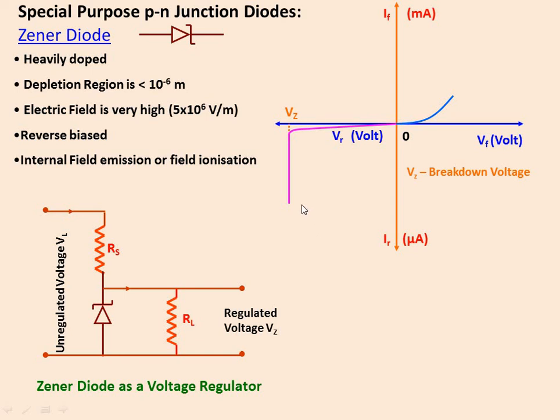But if the diode is very lightly doped, the breakdown of the junction will occur at a high voltage. Are we clear with this? So depending upon the doping we can have these particular breakdown values. Regarding this we have already discussed avalanche breakdown. So based on the doping alone, when we heavily dope and operate in reverse, it gives us the Zener diode. Are you getting the point here? Clear for us, right? And the circuit symbol also I have mentioned here.